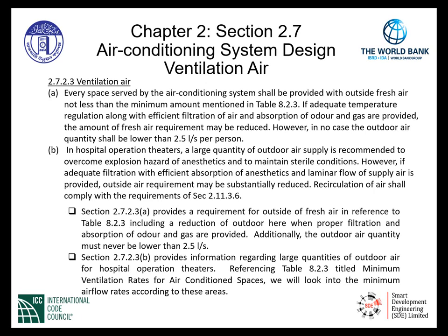Additionally, the outdoor air quantity, again, must never be lower than 2.5 liters per second. Last, section 2.7.2.3b provides very specific information and requirements regarding hospital operation theaters.